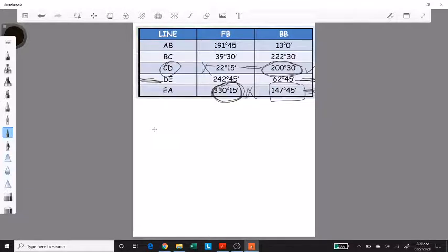So once we do this, we can find out the error at every point. Error at the point A, point B, and point C. Because point D and E we have already established are free from any error. So we can calculate the errors at the point A, B, and C. And whatever error there is at the point A, B, and C, the errors would be the same in every reading, because how much that magnetic substance affects the reading is constant.